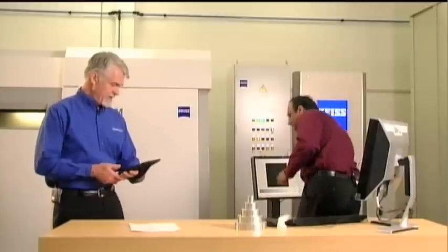Okay. And actually, right now is probably a good point. Somebody already has a question. Lance from Lam Research wants to know, what is the accuracy of computed tomography? The stated measurement accuracy of Metrotom is 9 plus L over 50. So if you have a 50 millimeter part, measurement uncertainty is plus or minus 10 microns.